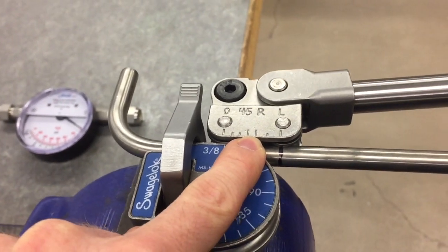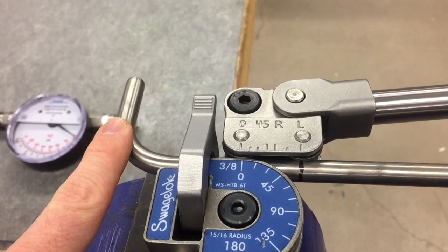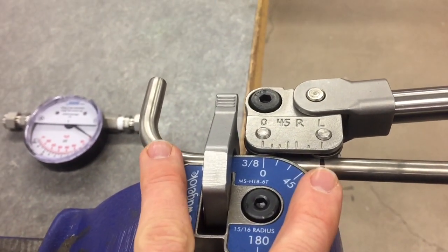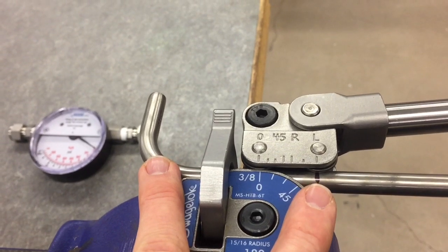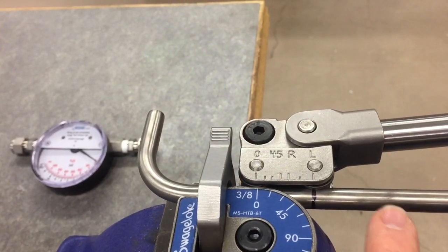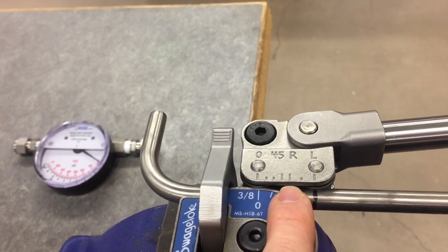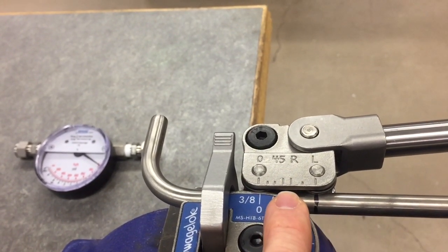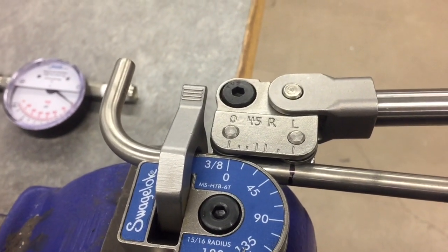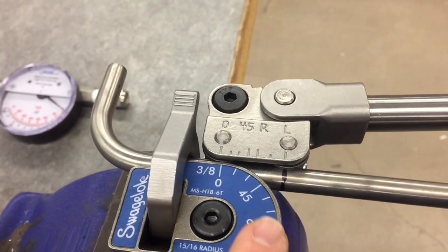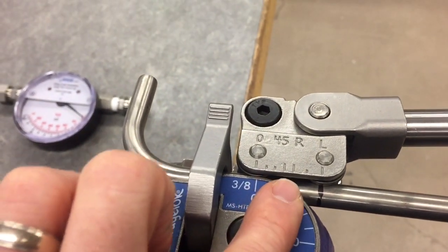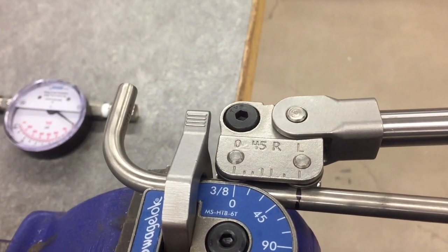So we got the right measurement, right? Because from the center of here to the center of where our tubing is going to be bent is going to be 3 1/8 of an inch. If we wanted that same measurement, but had this bend over on the right side, we would need to use the R for bending, lining this line up with the R for bending our 90. About 90% of the time the L gets used for bending the 90s. We usually always use it out to the left. The R is sometimes used for tighter bends.